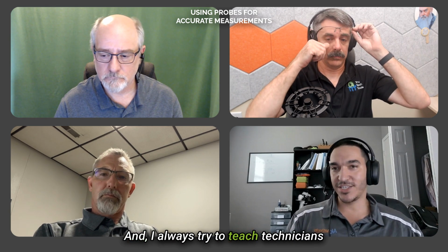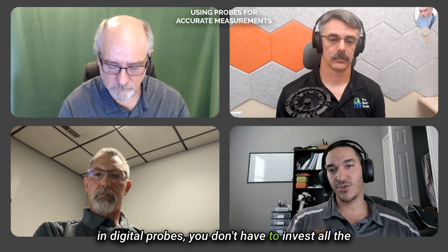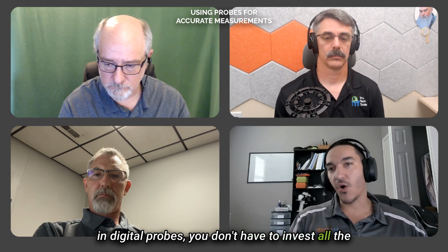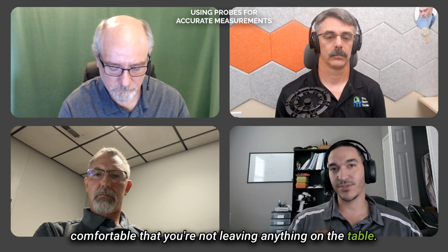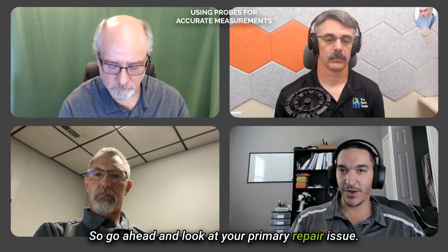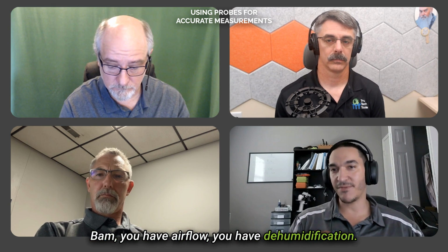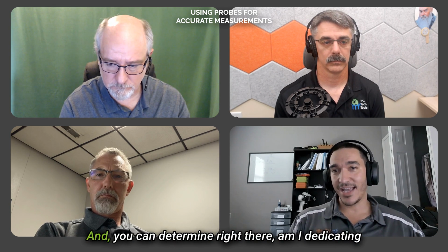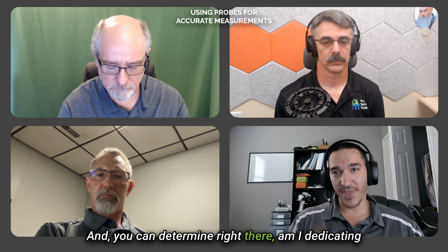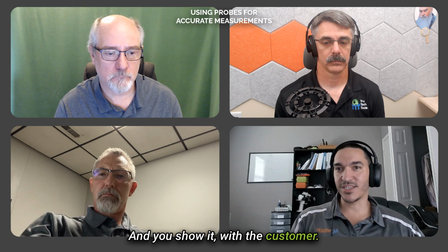And I always try to teach technicians, inside out with measureQuick and digital probes, you don't have to invest all the way up to a 40-minute service call to at least feel comfortable that you're not leaving anything on the table. So go ahead and look at your primary repair issue. Go inside, put 2 psychrometers on. Bam, you have airflow, you have dehumidification. You have a pretty strong indicator of system capacity, and you can determine right there, am I dedicating an additional 20 minutes to this diagnostic, or are we good to go? And you show it to the customer.